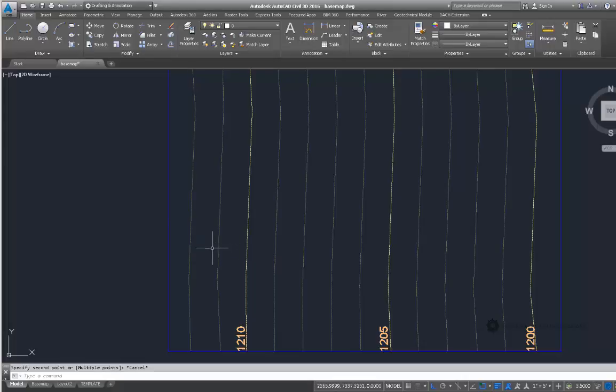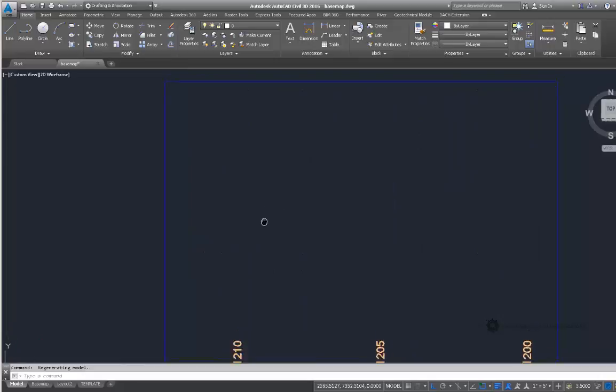But one thing you have to remember when you use this tool is that these two contours are not coplanar. If I rotate this in 3D and take a look at this from a sideways view, you can begin to see that there is a gradual slope occurring. So if I use this measure tool and measure from here to here, we're not getting the true horizontal distance. We are instead getting the hypotenuse of the triangle. Remember that this is actually looking in section view, so this is a 1 foot elevation change, and we're just picking up the hypotenuse by measuring from there to there, because we're snapping from here to there.